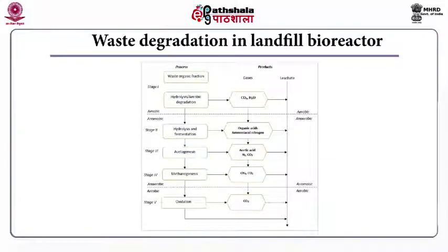If you see, during aerobic degradation you can observe carbon dioxide and water being produced, and in hydrolysis and fermentation you can find organic acids and ammoniacal nitrogen. In acetogenesis you have acetic acid, hydrogen and carbon dioxide generation, and in methanogenesis you have methane and carbon dioxide generation, and finally in the oxidation phase you have CO2 generation. So, these are the 5 phases of degradation of waste within a landfill bioreactor.